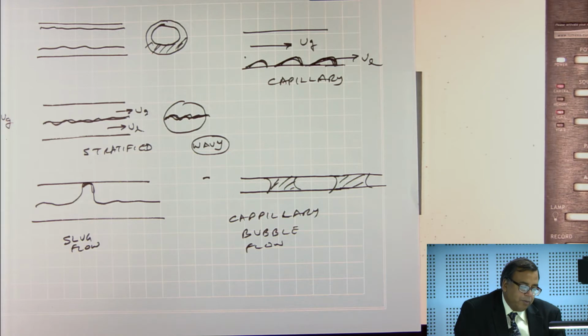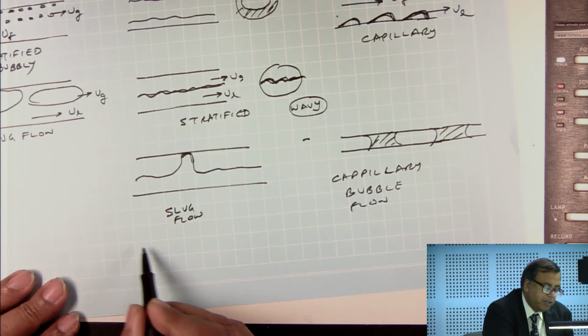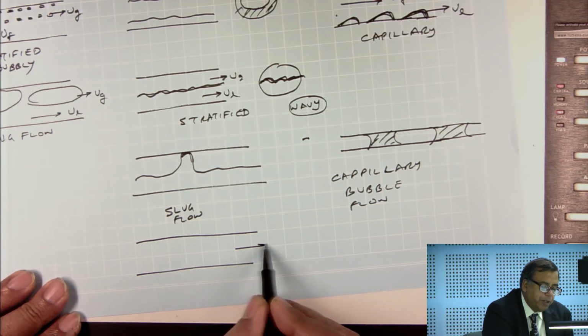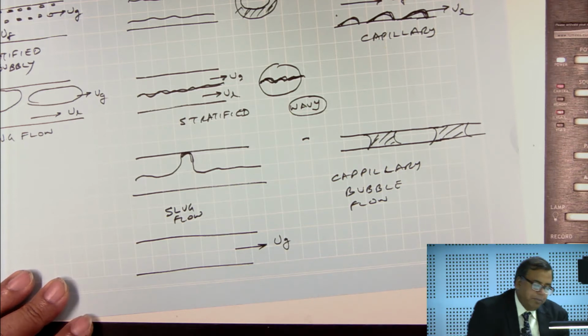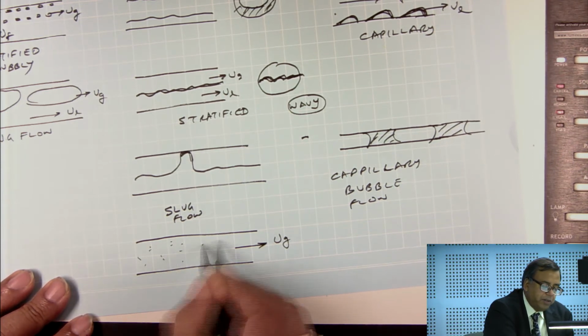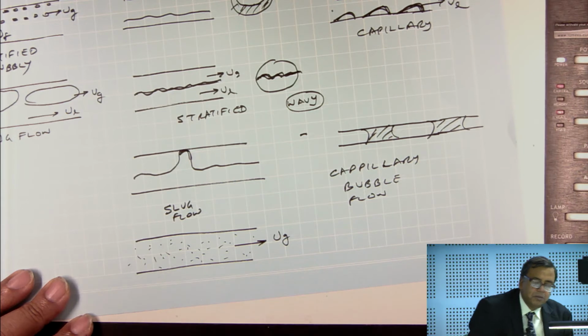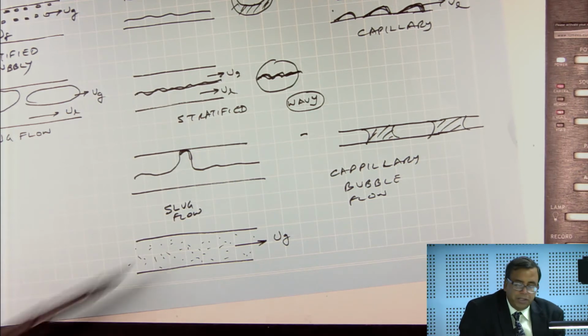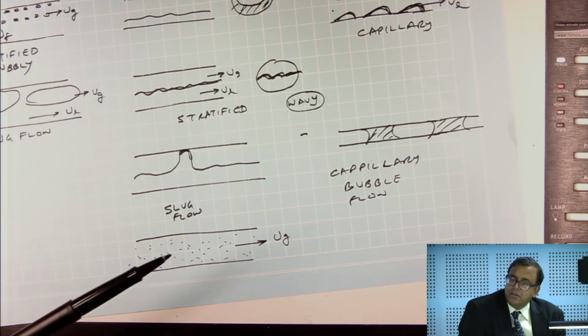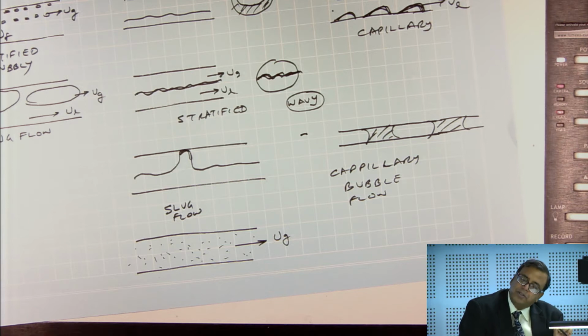Okay. Now, when it comes to power plants, there is one other type of flow that comes in, and that is known as mist flow, where you have pure vapor in the pipe, but you have dispersed droplets of superheated liquid like a mist, and these droplets impinge on the heater surface and they bounce off like billiard balls. The reason is, every time they are touching the hot surface, it is generating steam, and the steam causes like a rocket engine effect. It bounces off like a rocket nozzle essentially.